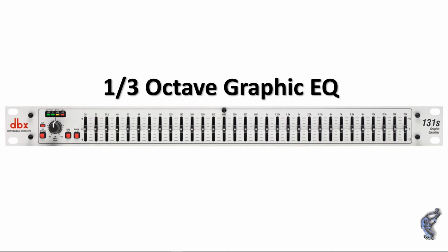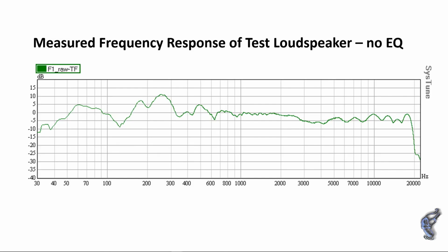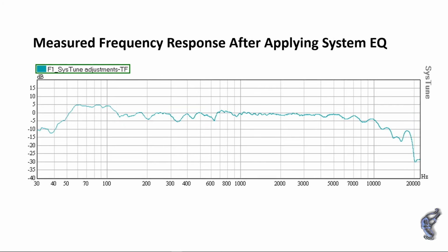We want our loudspeakers to have a smooth frequency response. Not only does that help our overall music mix sound better, but it also helps us minimize issues like feedback. The reality is that most loudspeakers are far from smooth, let alone flat. So we insert an equalizer in the signal path, which we can use to smooth out the frequency response of the loudspeakers. It's unlikely that we'll ever achieve a ruler flat response of each loudspeaker, but careful adjustments can definitely